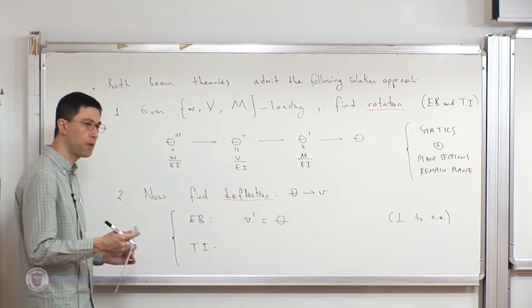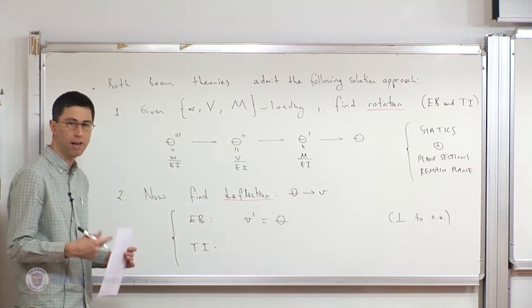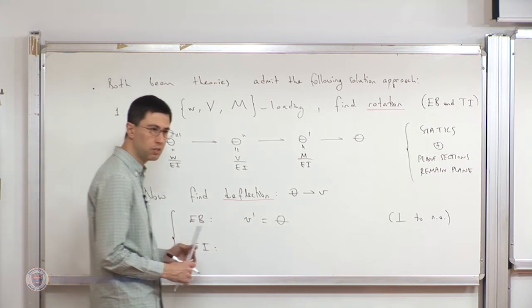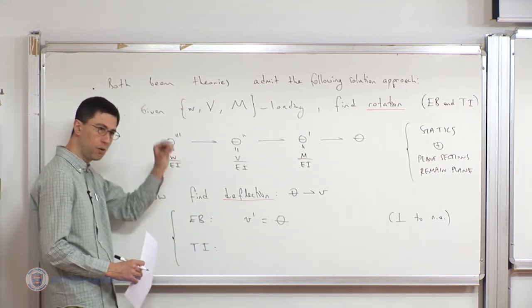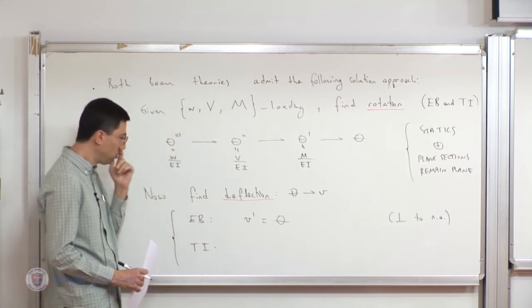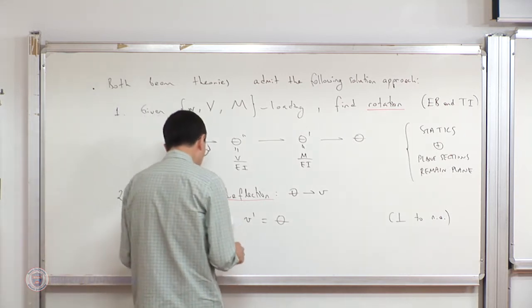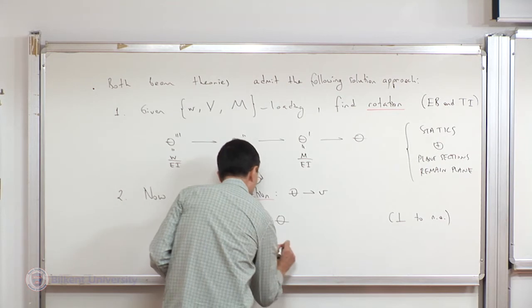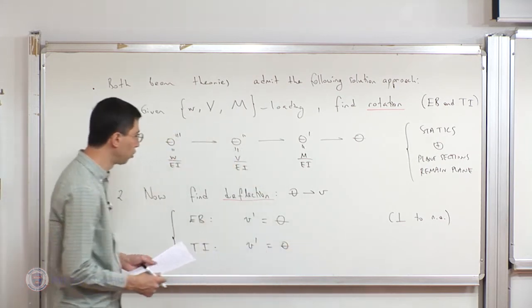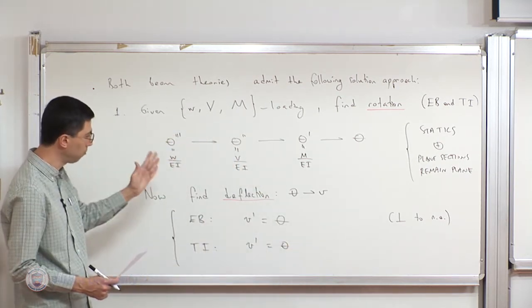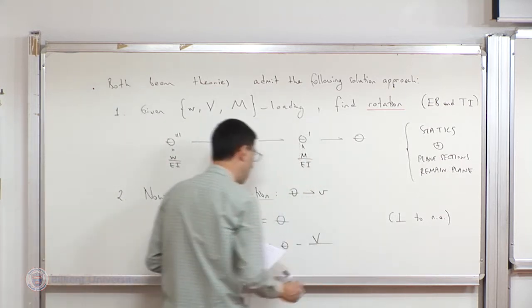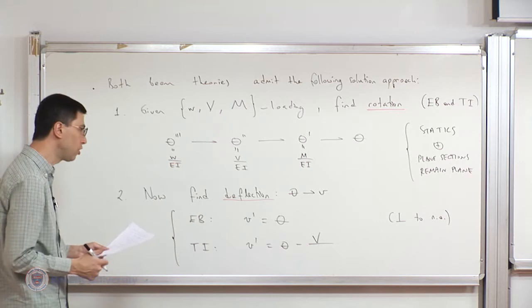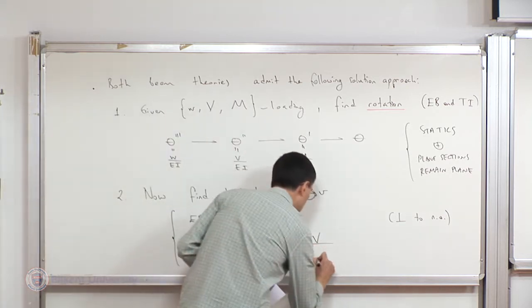And we account for that in an approximate manner by assuming that the shear strain is approximately constant along the height of the beam, which of course is not true. But if we make that assumption, we obtain that V prime is not equal to the rotation of the cross-section, but rather there is a difference that has to do with the fact that the slope changes also due to the presence of the shear stress.